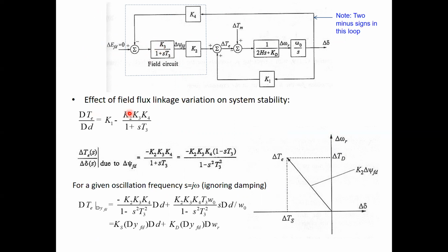And then we want to understand the rotor angle delta which you have here. It is actually the voltage angle, right? Or the MMF angle basically. And the MMF angle corresponds to the flux. That means how the flux distribution takes place in the generator. In fact, the rotor angle is the angle difference of the main field MMF and the resultant field MMF, right?